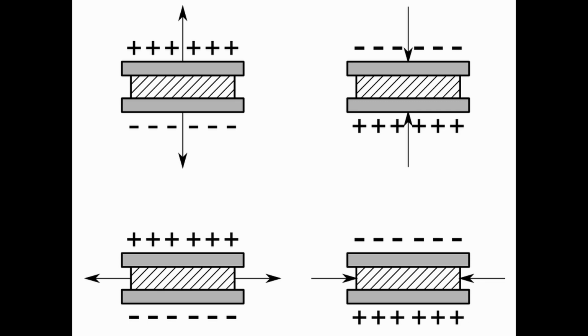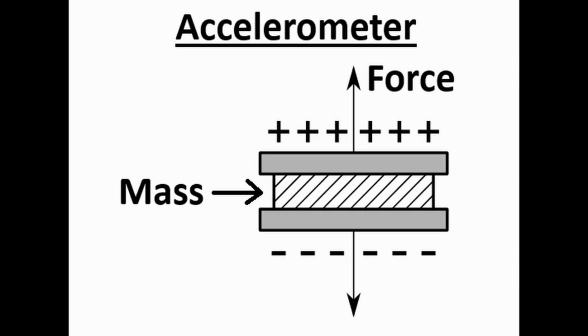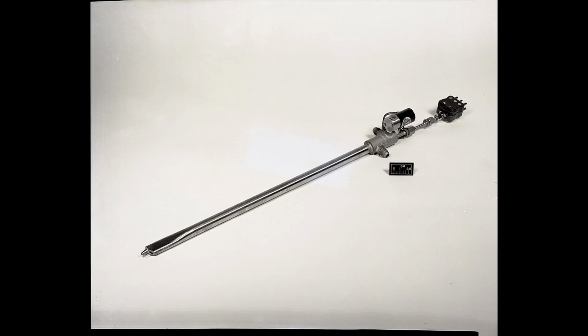Piezoelectric materials are fascinating substances that have been used in many kinds of sensors. In particular, these materials develop a charge across their surface when stretched or compressed. For example, piezoelectric crystals can be placed around a mass that would compress or stretch the crystals with abrupt applications of forces. This produces an accelerometer.